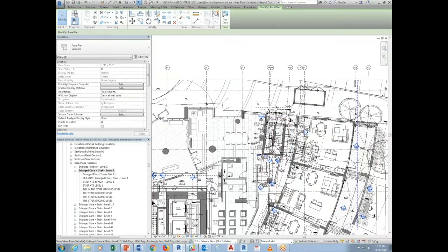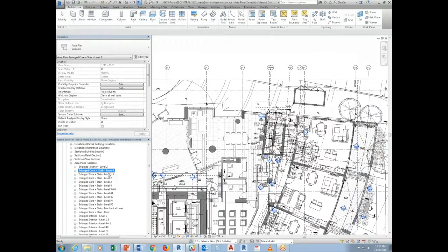The nicest thing about this is that you're not dimensioning all over the place. You're just keeping it to that particular view, and then you just dimension that. Okay? It's a very good system. Once you understand it, all I have is one plan that has all its views, all kept within that level. As soon as you create a dependent, it will go under that.